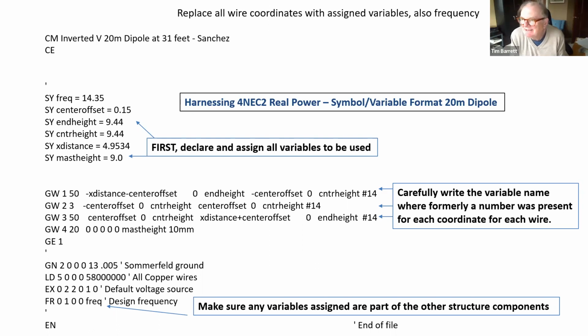Now, if you made this antenna with 4, you would get almost identical results. But to be formally correct, your observation that you want to have an odd number of segments in the part of the model where you're going to place the transmitter is a good observation. All right, thank you. Because you want symmetry around the transmitter. Absolutely. And I had forgotten to ever say that, and I'm glad that you asked the question.